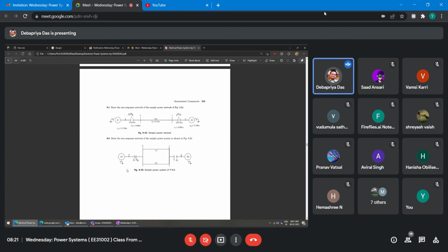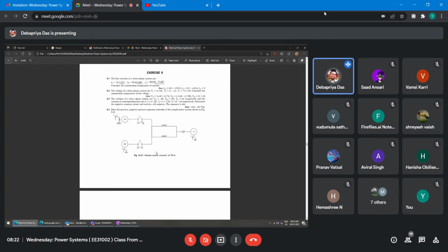So this side will remain open. Here star grounded, but this side is ungrounded. So this side it will remain open. Similarly, the star grounded delta, it should not be connected to the reference line. This should remain open, right? So you will draw this as an assignment.